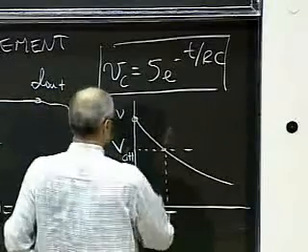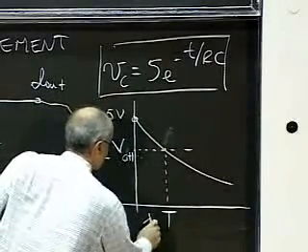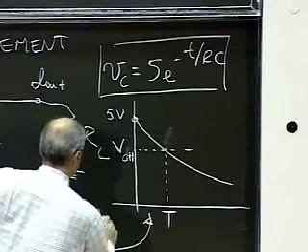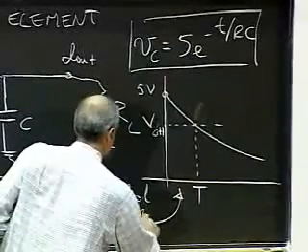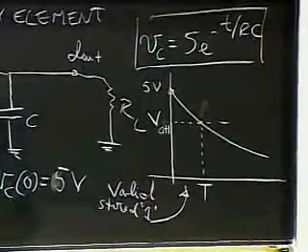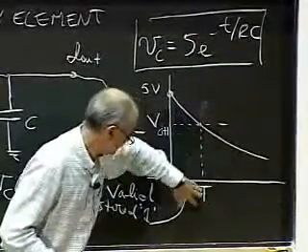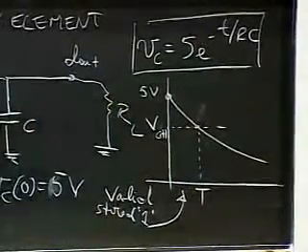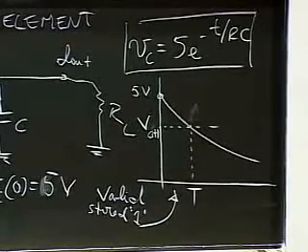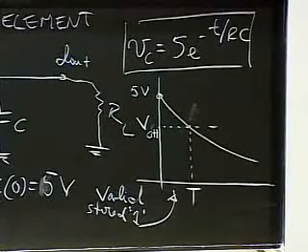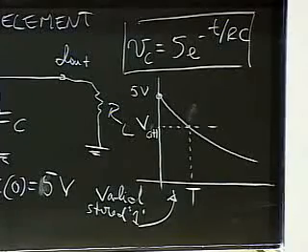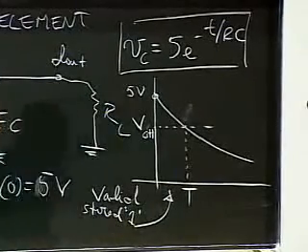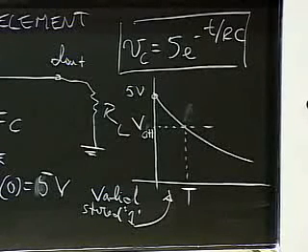So this is the only period in which I have a valid stored 1. Because once I go beyond capital T here, I've crossed the legal limit for threshold for discriminating a high output, and from then on the output is no longer valid. So this memory is good, provided time t is less than capital T.